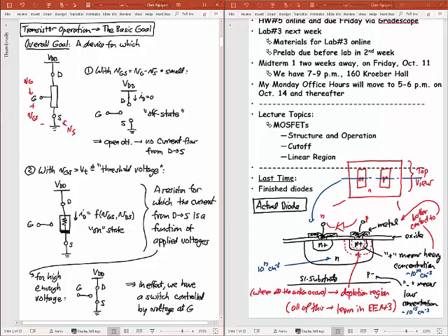And so what this is that when this voltage VGS becomes greater than my threshold voltage VT, then this actually turns the device, quote, on. And what it means to turn the device on is I have some resistance now between my drain and source, which means current can flow. And notice I've drawn this resistance like this. It is basically a nonlinear resistor because now the value of that resistance depends on the value of my voltage VGS.